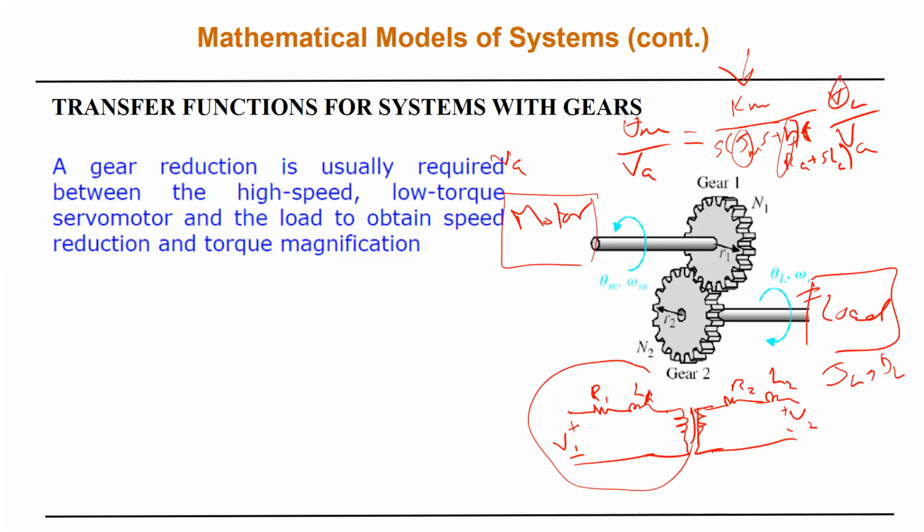Put it in there through what? Multiplying it by the turns ratio squared, I think. Yes, something like that, there is a factor. We would like to modify J and B and make them what we call equivalent. Let me find J equivalent and B equivalent on the motor side.